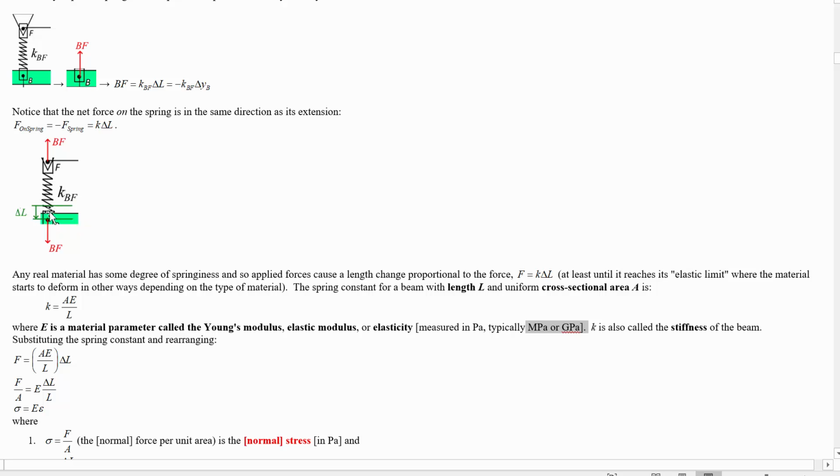And then what about if you put them in series? If you take a spring and then put another spring on the other side of it here, then when one of them extends, for the forces to balance all the way along, they each have to have an extension that's only half as much as they would have had if they were the only spring there. So if you take springs and stack them in series, that reduces the total spring constant, right?